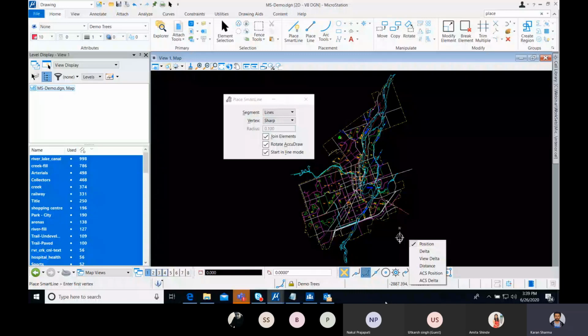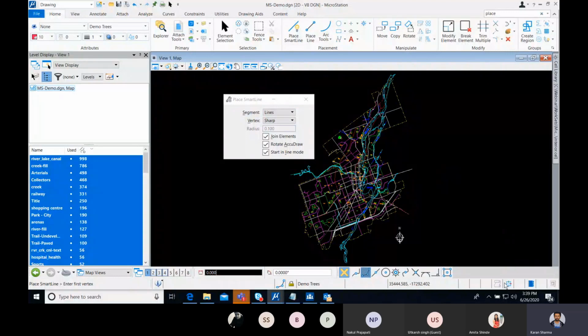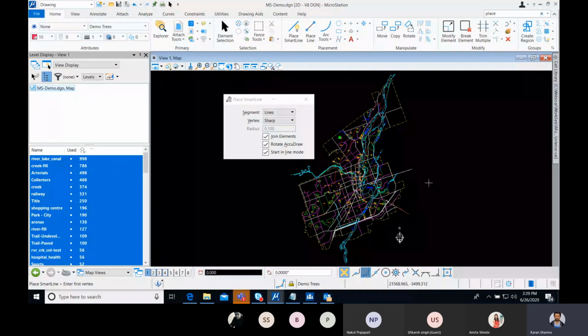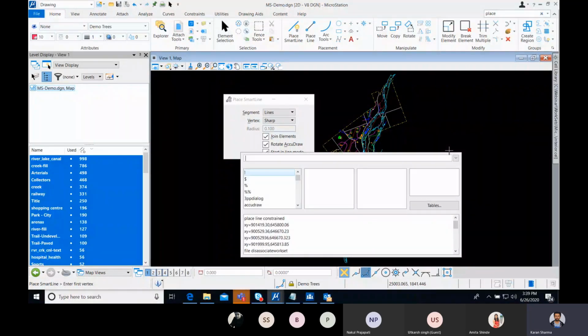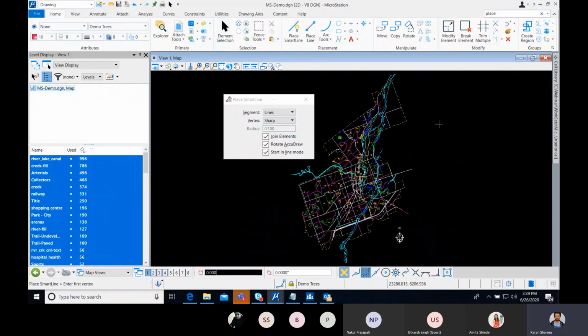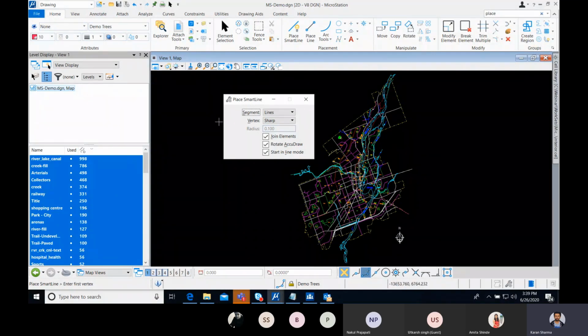Then this one thing I want to tell you is quite important, and you'll face this while using the software. This space, if you're able to see it, tells you where your current focus is. Depending on that, you'll be able to use your shortcuts and mouse operations. There are function keys from F9 to F12 with different purposes. I'll just show you that. If I press F9, my KeyIn window will come. So if I don't want to go here and select from this part, I can just press F9. This window will appear. If I press F10, it will bring focus to this tool settings dialog box.